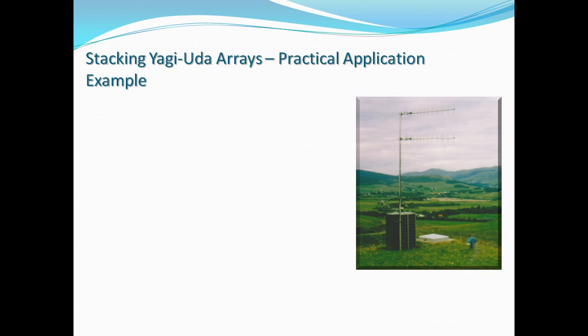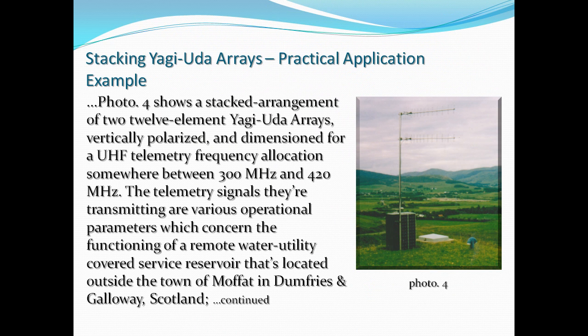Stacking Yagi-Uda arrays, practical application, example. Photo 4 shows a stacked arrangement of two 12-element Yagi-Uda arrays, vertically polarized, and dimensioned for a UHF telemetry frequency allocation somewhere between 300 MHz and 420 MHz.